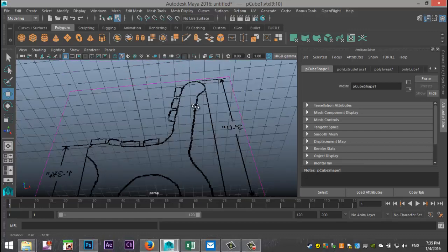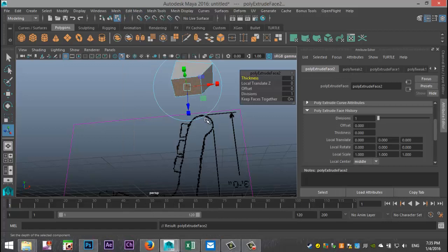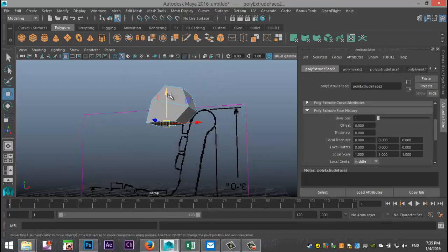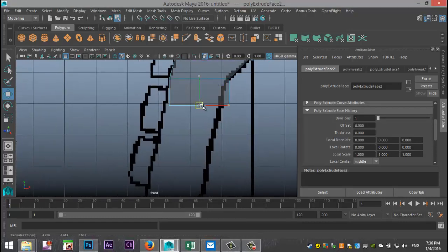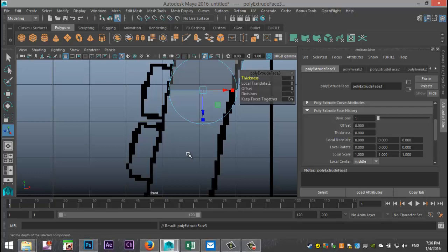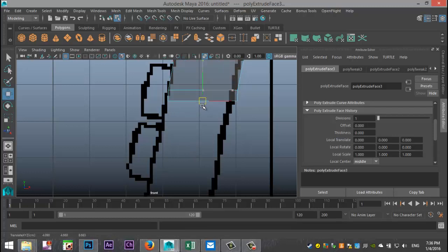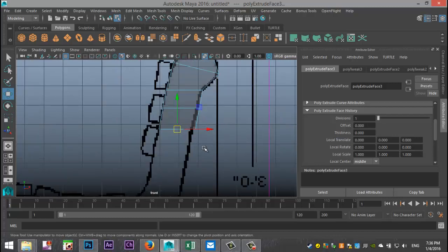All right. We're going to go to the bottom part here, right click face, Edit Mesh Extrude, hit W again, and kind of pull that down. And we're just going to bring that in here, and we're going to focus on the left side for now, and we'll tweak the rest later. Okay. Hit G to repeat, W to pull down, and try to keep spacing roughly the same. G to repeat, W to pull down, GW.